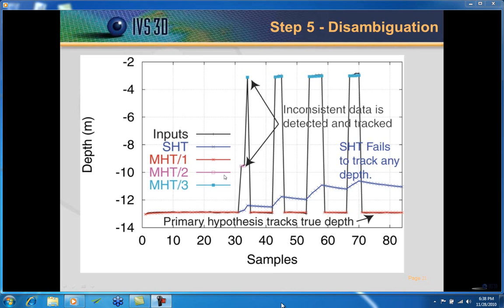It says, okay, I now have all these different estimates of what the depth might be at this node. Now let's decide which one Cube is going to take, and how Cube decides that is based on what you select. The number of samples is normally the one that works best, so the popularity contest, basically: who has the most wins.